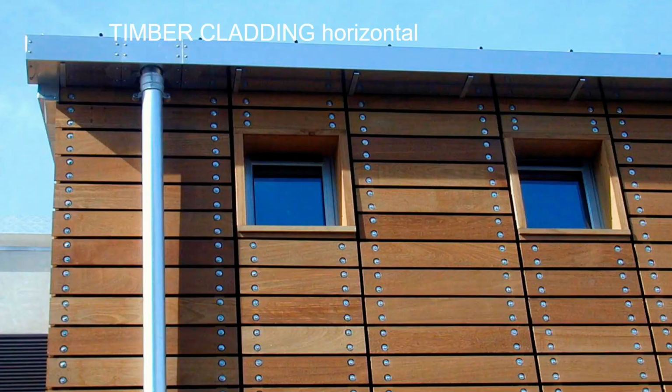Earlier on when I mentioned that oak needs washers and pre-drilled holes, this is an example of an oak wall, and we can see all these fixings here. Now the reason that oak needs that is because the board is so strong that if we were just to nail through it, as it expands and contracts, it's going to move in and out along its length and along its width and across its depth, so there's a possibility that these nails would actually start to pop out.